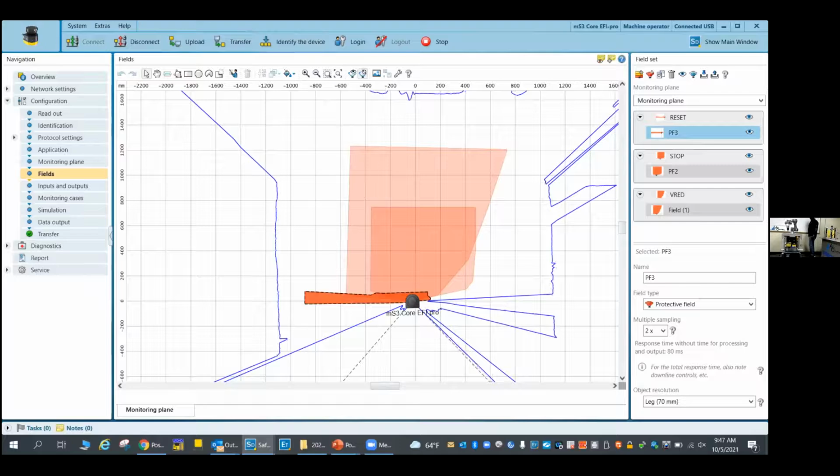and he's meaning well, but look at that. He's come back this way so I can see you. You're in the field. Come back this way, right? So before he would have gotten back there, see, we're in this red field, which we didn't put in the program. That would be the field that would be the no-go zone. That would tell the robot to stop and to go into manual restart because somebody went behind the robot. So go on back there. So without that, you're kind of in trouble here because our maintenance guy could get hurt. So come on out. So here's maintenance guy, robot right here, smashing the head.